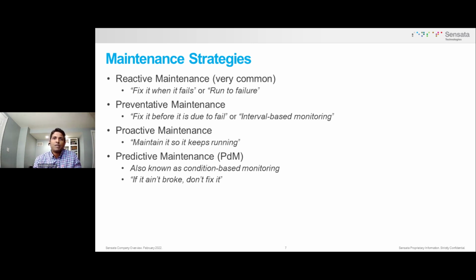For that reason, you must always keep spares. That increases your inventory cost and also labor cost to repair the equipment after a catastrophic failure. The advantage of using this kind of strategy is to reduce the cost of performing unnecessary condition-based monitoring. The disadvantage is that the asset will always fail. So when do you use this kind of strategy? You use it when you have non-critical machines that are inexpensive to repair.